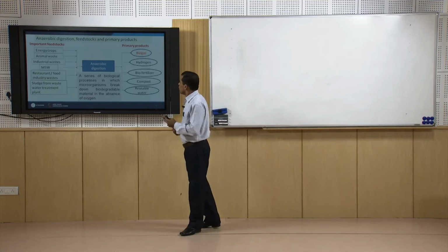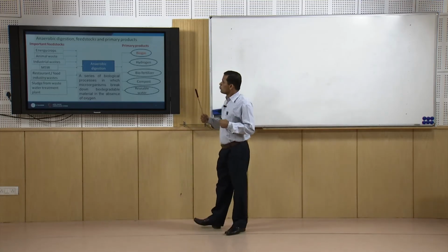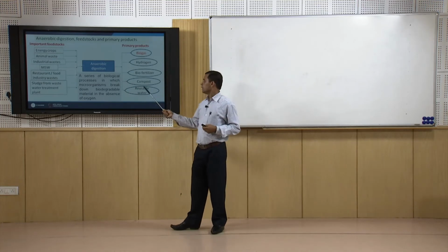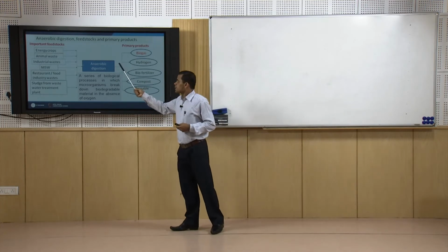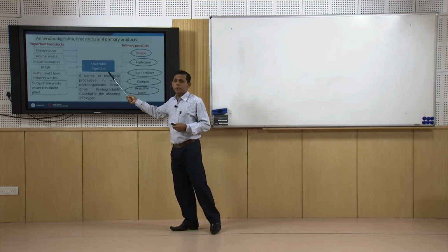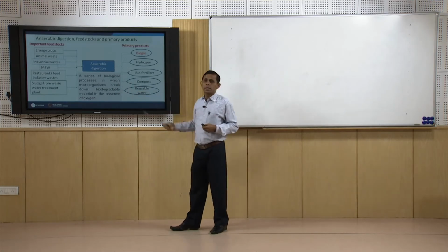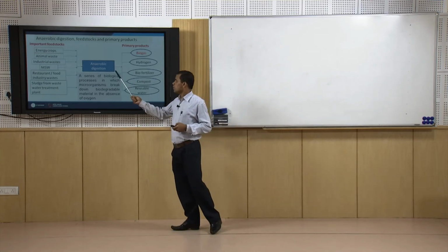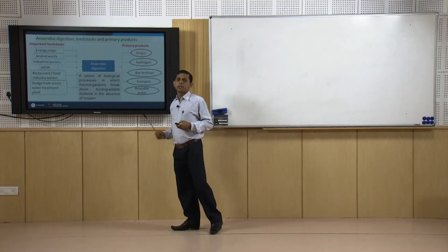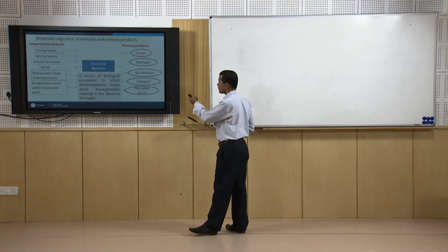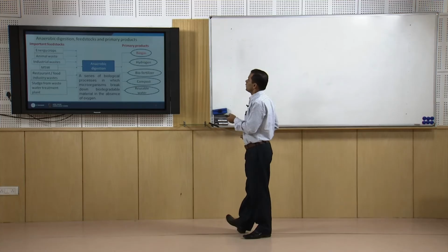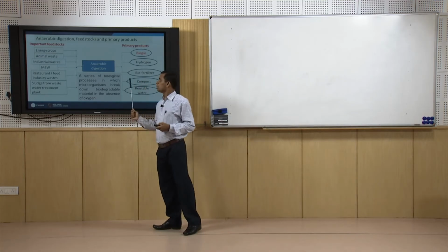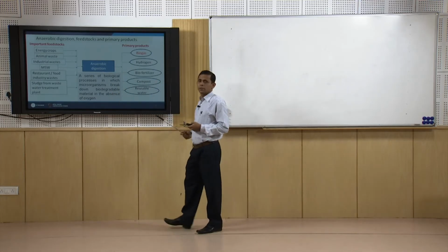That is why people are trying to improve this process in terms of low requirement of water. So, the 8% slurry which is conventionally used for anaerobic digestion, in wet anaerobic digestion, is going to be upgraded to dry anaerobic digestion using up to 20% solid in the slurry. So, these are the feedstocks and these are the primary products which we can get through the anaerobic digestion route.